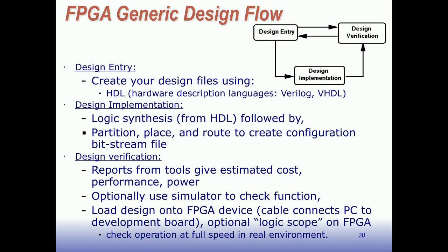Once you have that, you can test it and verify your design. The tools that do the logic synthesis, partitioning, placement, and routing will give you an estimated cost, performance, and power, even before it gets mapped onto the FPGA, because they know approximately how much space is needed, what the critical delay will be, and approximately how much power. So you can use that to iterate and change your design a little bit. You can use a simulator to check the function. There are simulators that will simulate at various levels, either at the Verilog level or at the mapped level.